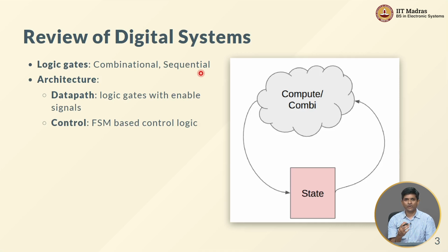So, that allows us to implement some kind of a controlled state transition. Only when the clock comes, the state of that flip flop, the output of the flip-flop, will change, which means that as long as the clock does not transition, I can retain that state. I have some kind of memory associated with my system, which I can then reuse and use in order to perform computations in a systematic manner.